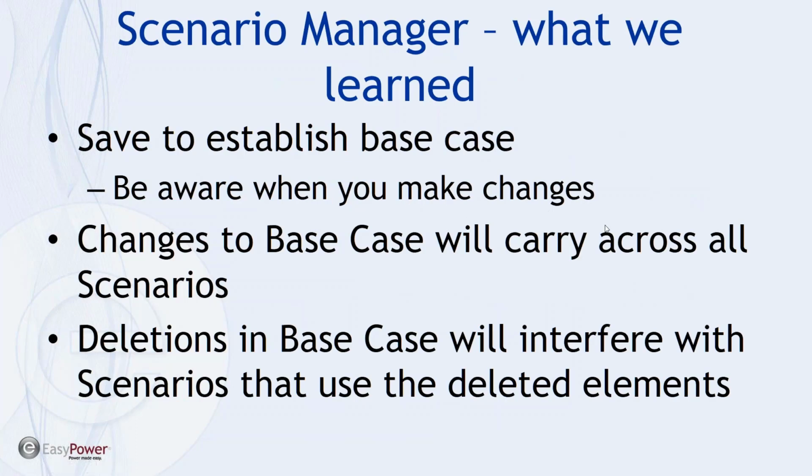The guideline that I'm suggesting is you want to save your base case, and be aware of what you're saving when the tool inquires if you want to save as you're closing out of it or going to another scenario. Any changes to the base case will carry across the scenarios. This was the question that I got multiple times: oftentimes we'll design a system using either generic or one manufacturer, and when we have discussions with the client, they want to use a different manufacturer in one case or across the board, and so we need to change the base case conditions. Will that carry across all of the scenarios we've created? The answer is yes, and that's why I'm suggesting you want to be a little bit careful what you've developed off of a base case, and then when you make changes to it, what's going to be null and void.